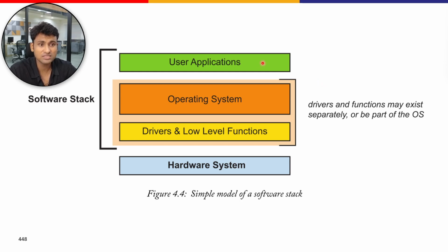And at the top of the stack sit the user applications. These are software programs that perform the end-user tasks such as data processing, control algorithms or graphical user interfaces. These applications rely on the OS for resource management and use system APIs to perform tasks like file handling, network communication or sensor data processing. In the context of a Zynq MPSoC, user applications may also include custom software that communicates with hardware accelerators in the PL using dedicated drivers and APIs provided by the OS.